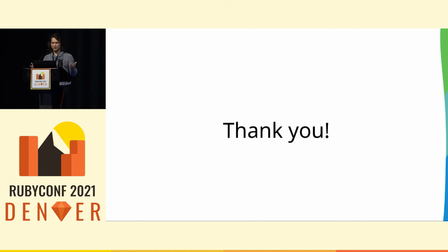So, particle filters, various filtering techniques where you have a preset map, and the robot looks at its sensors and does some calculation where it says, what's the most likely place for me to be? And it continually updates. If you're interested, Bayesian filtering techniques and things like that are the thing to look at. There's a lot there.